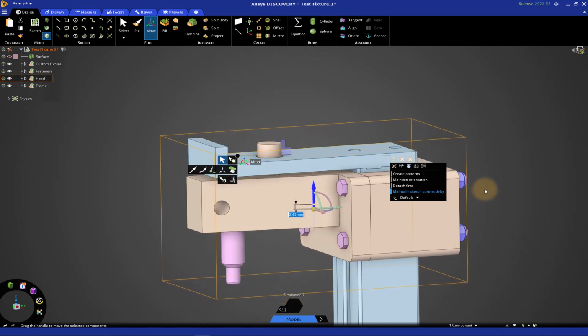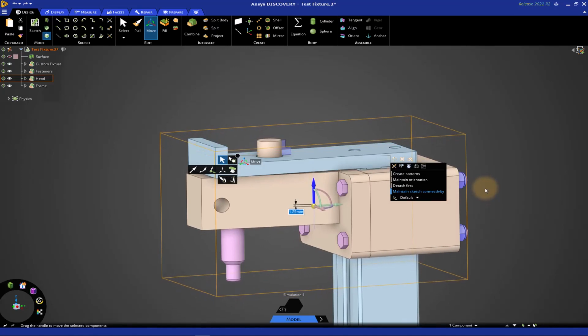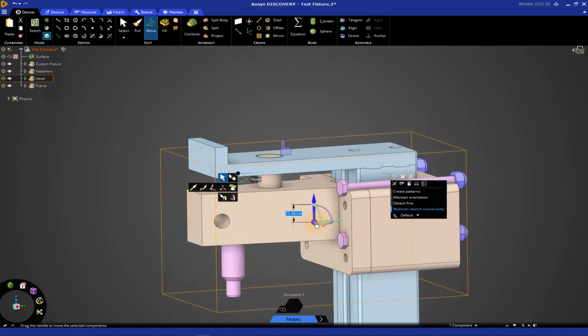Now here, if I want to parameterize the position, I could drag the move tool to the proper reference, set up a ruler from the options over on the right to the necessary reference here, and then create a parameter with this icon next to the value. That will show up down in the lower right by clicking on this panel here and clicking on groups, and it will show that here where it could be renamed.